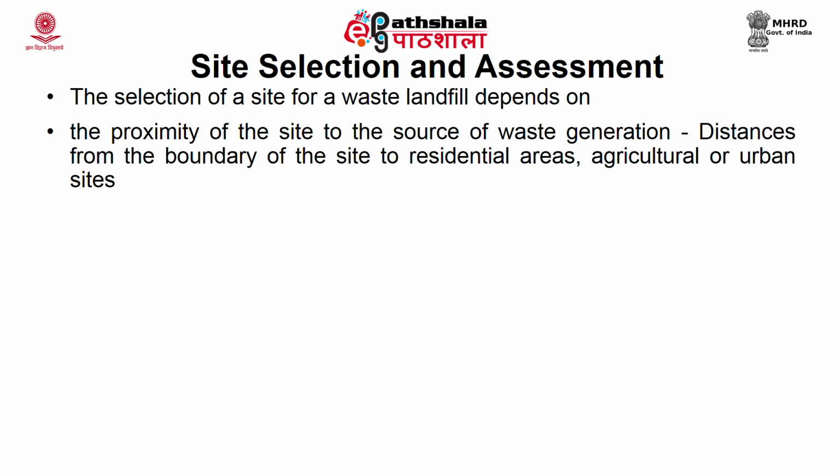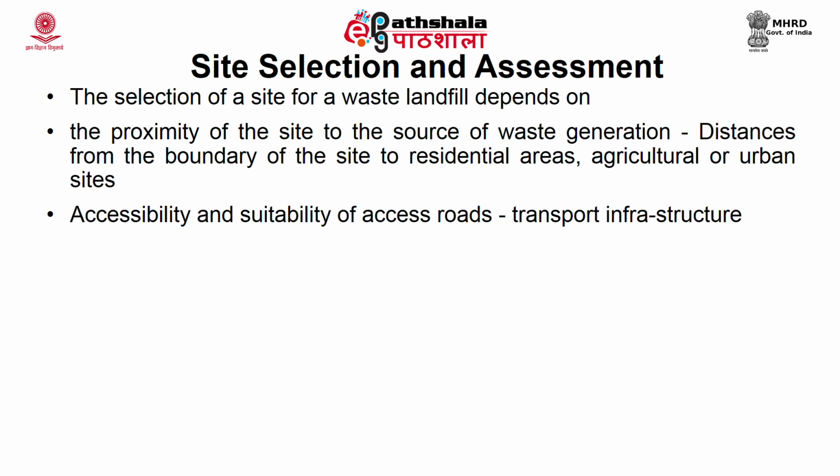One, the proximity of the site to the source of waste generation, and the distance from the boundary of the site to residential area or agriculture or urban site. This means that the waste site should not be close to a residential area, an agriculture area, or an urban site. These landfills are always located on the outskirts of the city, away from the city. But though they are located on the outskirts, they should still be accessible. They should have proper road connectivity, and the transport infrastructure should be good.